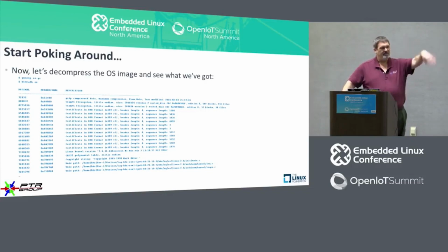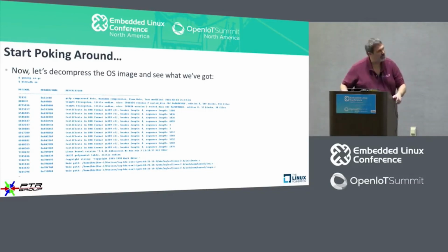We cut it off because there was a whole bunch of stuff in there that we couldn't make fit on the screen. Even that was a little hard to get to fit. But that was a really fortunate find, where by simply grabbing a hold of the firmware and doing a little bit of poking around in it, you figure out that it was a gzipped environment, un-gzip it, and then run Binwalk on it again, and you find all the good stuff that's inside of it.